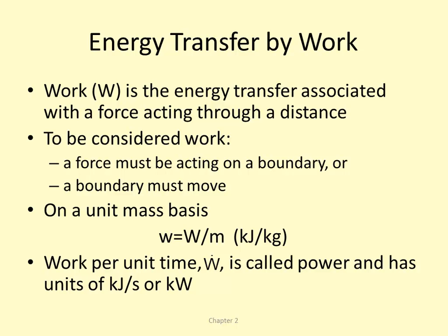So work is energy transfer as well, and in basic terms, it's the mechanical energy of a force acting through a distance. So to be considered mechanical work, there has to be a force acting on the boundary, or the boundary must move. And then again, on a unit mass basis, the lowercase just denotes the intensive property, which is work divided by mass. And then W dot is work per unit time, and it's also called power.